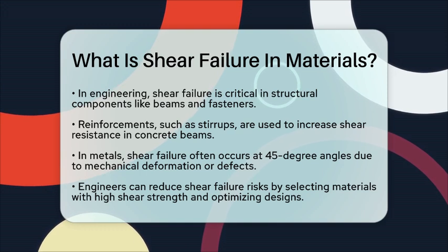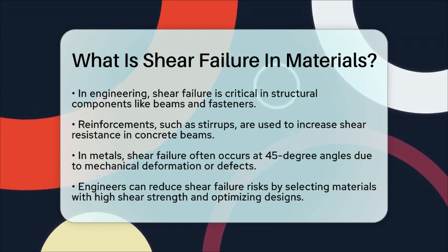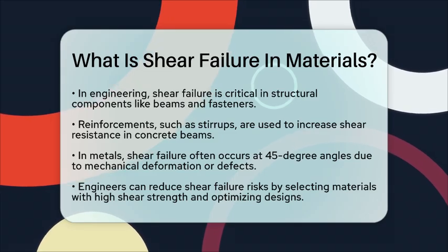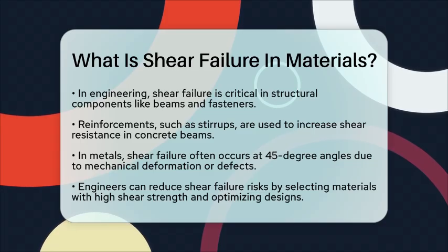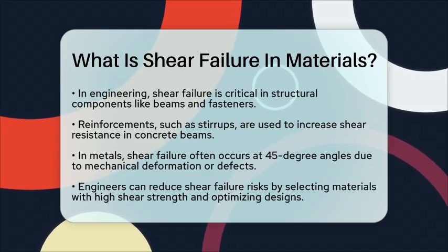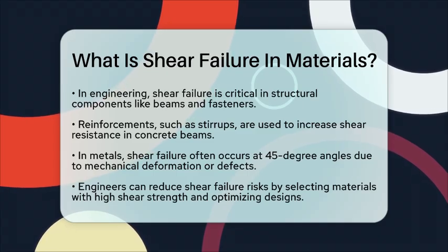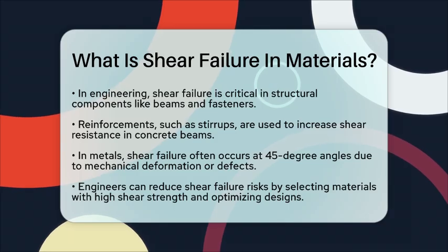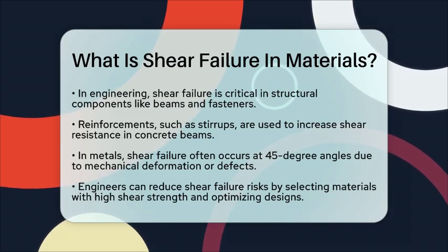To reduce the risk of shear failure, engineers choose materials with high shear strength, optimize designs to minimize stress concentrations, and apply surface treatments to improve resistance. Understanding how shear failure works helps in diagnosing product failures and mechanical breakdowns. This knowledge leads to better material selection, design, and manufacturing processes, ensuring safety and durability in real-world applications.